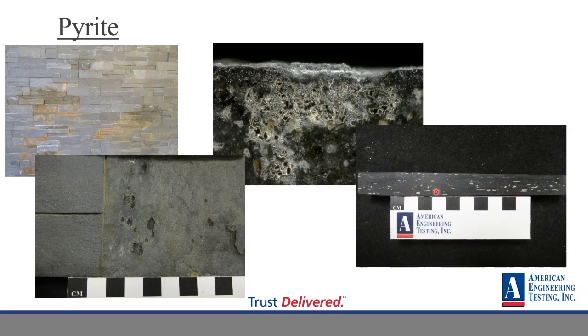So the stuff in the body of the rock, not exposed at the surface, most likely wouldn't do anything unless that stuff on the surface started to react bad enough and maybe cause planes of weakness or seams or cracks for water or atmospheric conditions to start to touch some of these lower ones. And then it's going to start to expand and possibly destroy some of these nice rocks used on this wall.